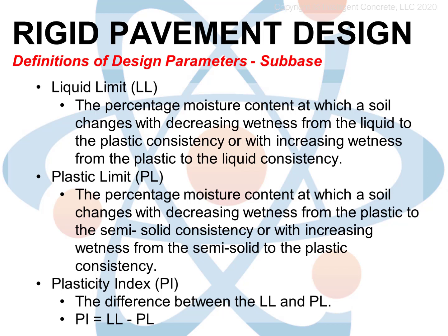The plastic limit is the percent moisture that causes a soil to change from being a friable solid, that is, it breaks apart under pressure, to being a semi-solid that you can start the process of being able to mold and remold. Imagine that you've got a little bit of soil in your hand and you're working it with your fingers, trying to get it to form into a cylinder or a ribbon.